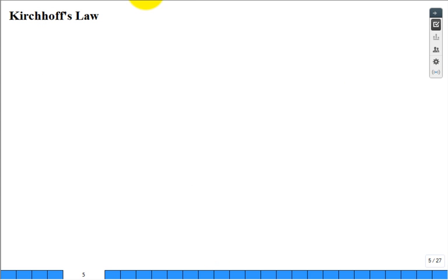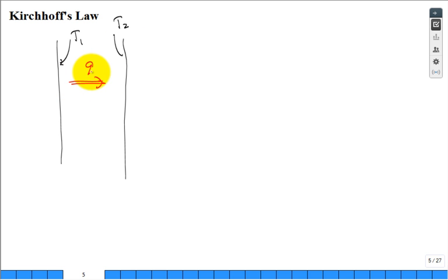So Kirchhoff's law, you can derive it for a little surface and a big surface. That's often done in the textbooks. I like to just do it for two large parallel plates. And these two large parallel plates are at temperature T1 there and temperature T2. Now, we're interested in maybe the flow of heat, the heat flux between the two, the radiative exchange between the two. Now, if the temperature of the one is equal to the temperature of the two, what do you think Q double prime is going to be if they're the same temperature?